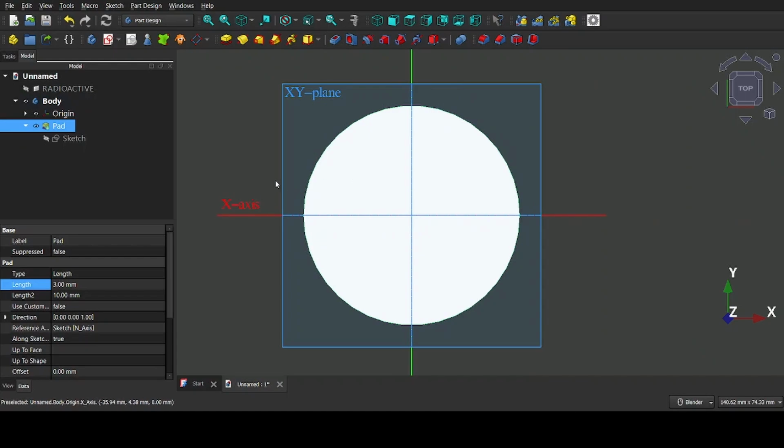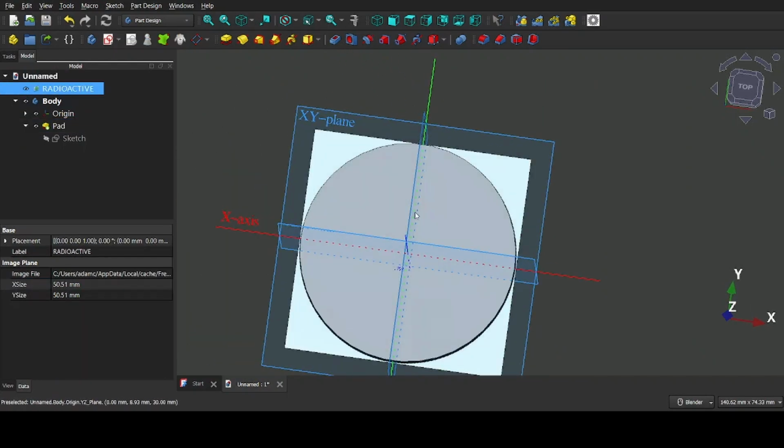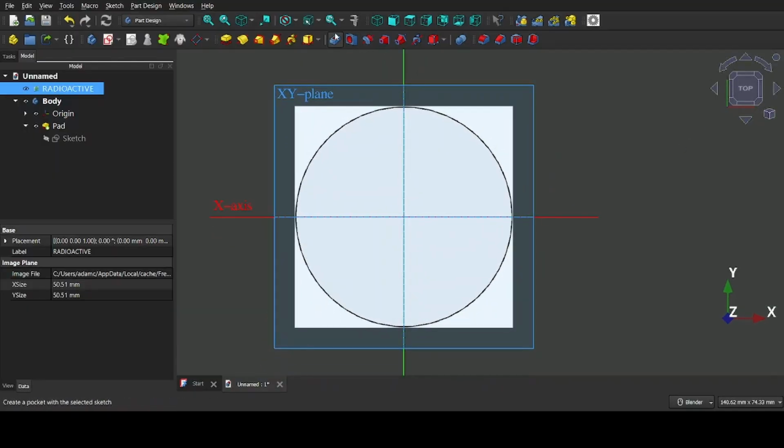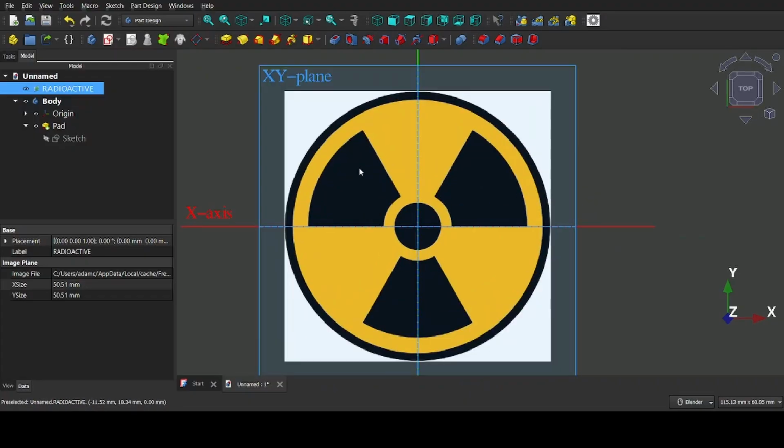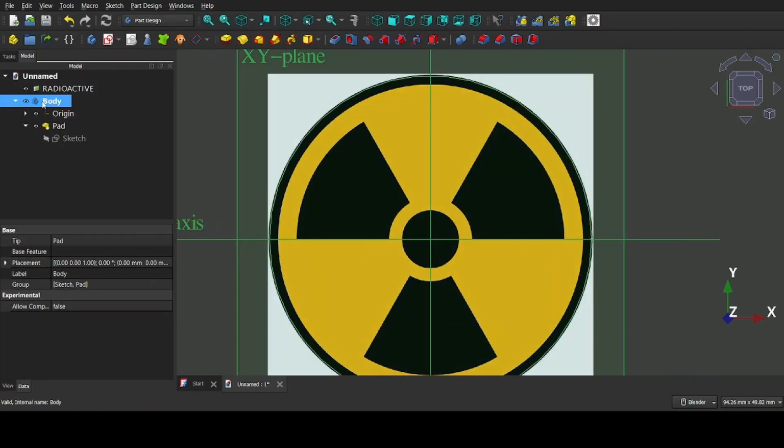When we created the pad, you notice that the picture actually disappeared. So one way to look at the picture is to change the view to wireframe. And you can do that by clicking up here again. For some reason, it's not recording, but when you enable wireframe, you can actually see the picture behind, because all it's showing is the outside of the circle perimeter.